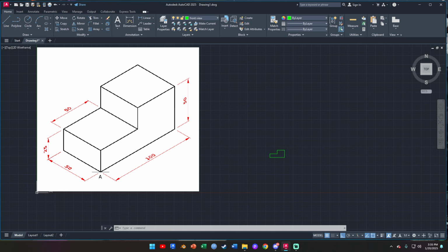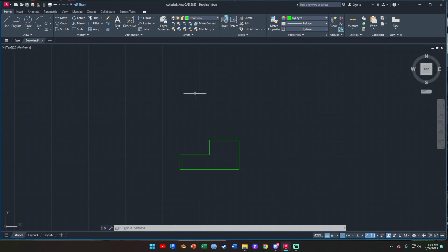If it was cavalier, we would have used full scale, and that means that you would have used the full 50 here. But for this example, I'm using cabinet, so we have to go half of 50, which is 25. So we can switch to this layer, which is called the receding line, and I'm just going to turn ortho mode off, right?